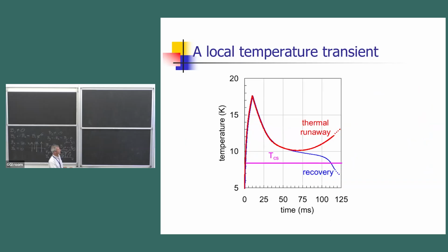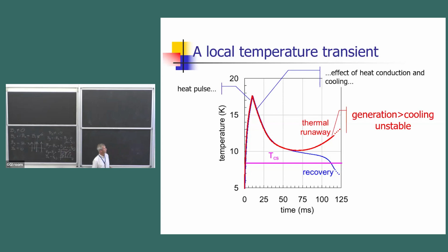So typically what you get is that the temperature following an event, an energy deposition, increases, okay? It may actually go above the critical current because it will start heating, but if you have a good shunt, we said copper, silver, they're very good conductors, you may still have a chance to come down in temperature because there's cooling, and then eventually recover the superconducting state. Or if it's too much heat with respect to what you can carry away, you have a thermal runaway, okay? So that's the effect of heating and cooling.